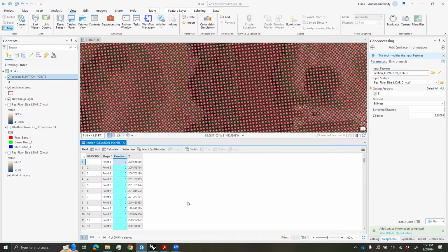The way that Rhino, or rather CAD exports in GIS, read elevation is that if there's an attribute table with elevation in there, so if there's a number in elevation, when you export that to CAD, it'll move that element to that elevation. So we need to simply take this number here and copy it to the elevation field. So it's easy to do.